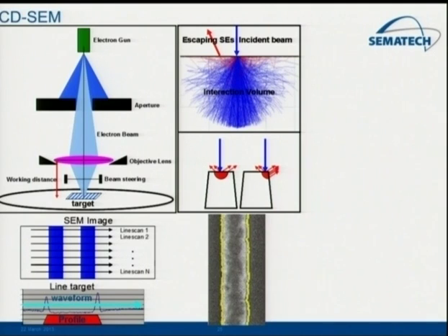When the electrons hit a feature, the secondary electrons come out of about the top few nanometers of the surface of the feature. If you get near the edge, of course, you have the electron beam hitting the edge of the feature with more of the beam penetrating and generating more of the secondary electrons, here represented by the red arrows. So the signal detecting how many of these secondary electrons are coming off is collected by the detector and used to form the video image.